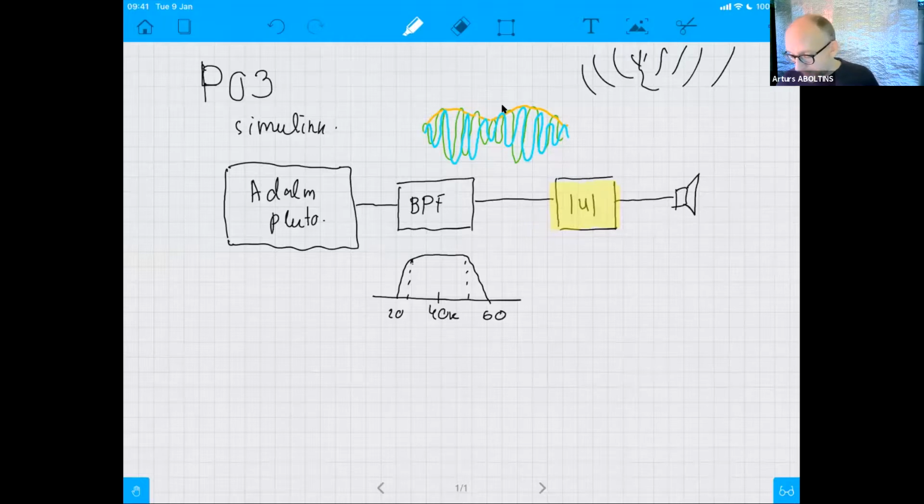The only problem is that a good bandpass filter usually requires a lot of components if it is a hardware filter, and if it is a software digital filter, it will anyway require a lot of computing resources to get a relatively flat passband, because if it is not flat, it will also change the spectrum of the audio signal which is played back, and this is not a good thing.